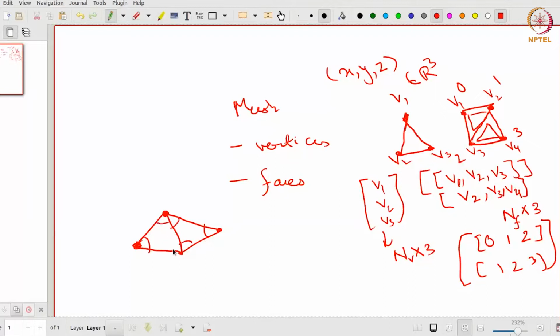So in the best case, what you would want is an equilateral triangle to have the best given property. So all these angles should be 60 degrees. And in the case you have a 60-degree angle that this particular vertex subtends with the adjacent edge, if you cover a complete circle with a triangle fan, you'll have exactly 6 triangles in a given triangle fan, because simply stating, 360 degrees divided by 60 degrees, you'll get 6 triangles.